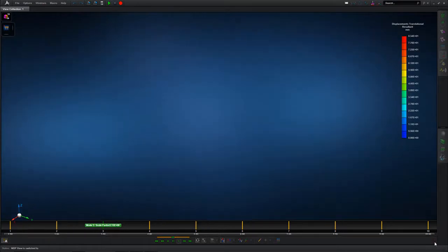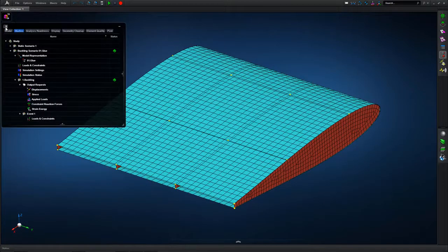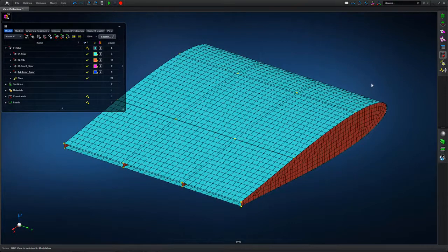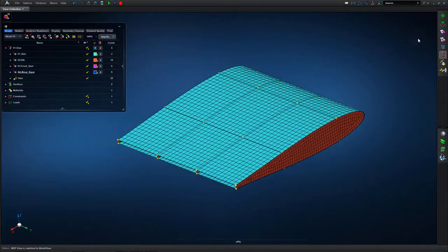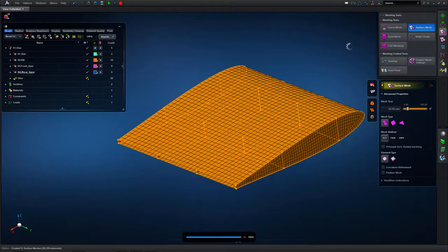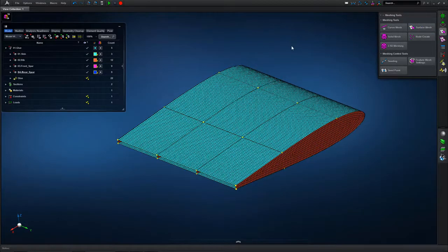So what we'd like to do now is just understand, if we were to make a change to the architecture of the wing box, so maybe changing thicknesses or rib layout or spar layouts, what the structure will do. So again, showing that we have no mesh congruency, we have the glue contact defined. We're going to change the mesh for the full structure and understand what impact that has on the global buckling factor that's calculated. So again, we've simply remeshed all of the entities.